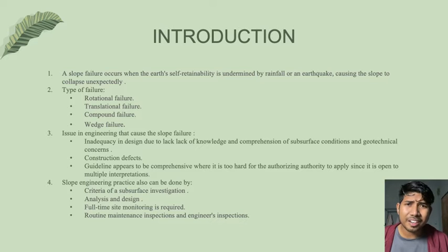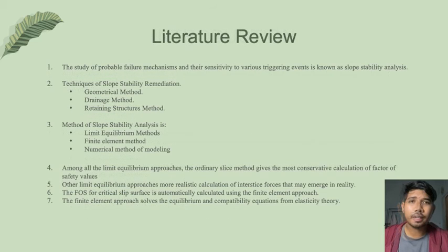The slope engineering practice can be done by, first, criteria or subsurface investigation. Second, analysis and design. Third, full-time site monitoring. And last but not least is routine maintenance inspection and engineering inspection. And now, let's proceed to the literature review.